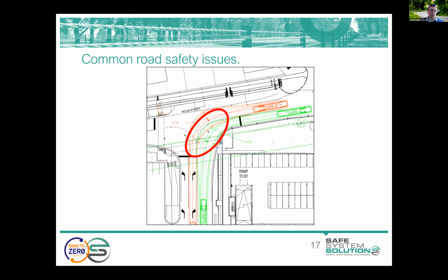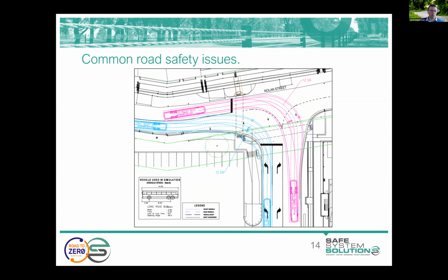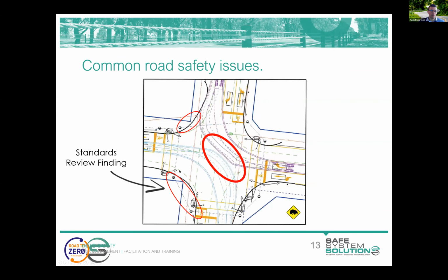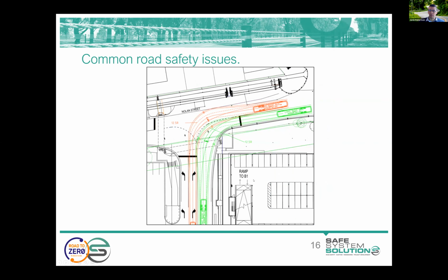Yes. So we typically would provide at least a 1 metre clearance between opposing movements. I'll just skip back a few slides. Some of the Austroads diagrams show some of the clearances, and similar clearances apply to right and left turn overlapping movements. So you certainly do want that buffer. And if you're plotting that 1/2 metre clearance line for both vehicles, it can be much easier to determine whether you've got that sort of 1 metre minimum buffer.